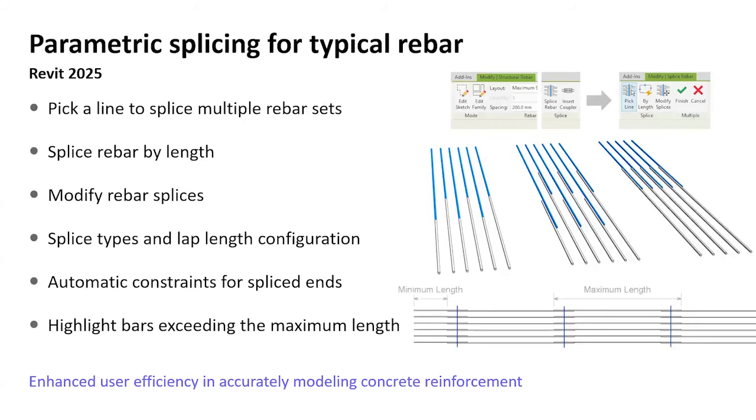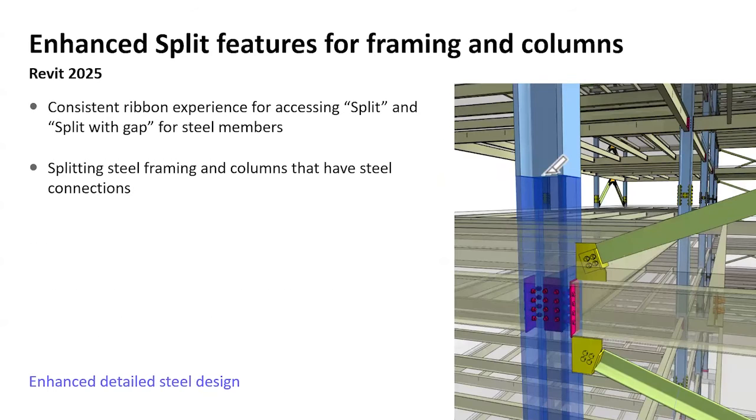There are some new enhancements to rebar. So the position, the slice, the length, and modify splices as needed. Alternately, you can also set a maximum length and a minimum length for run-out position. So structural engineers are getting some love in the new 2025 features.